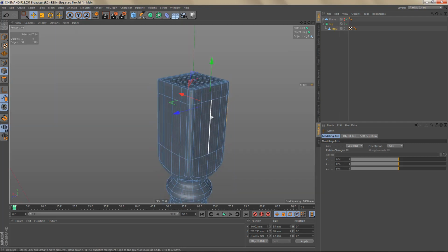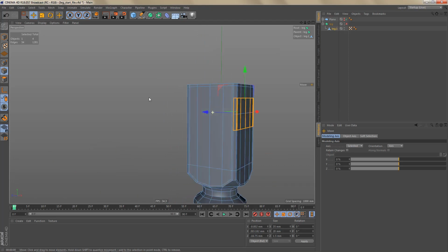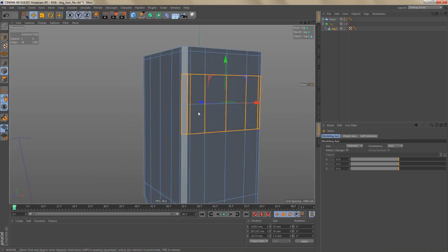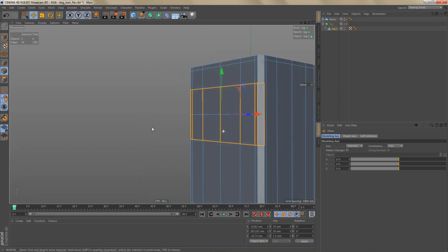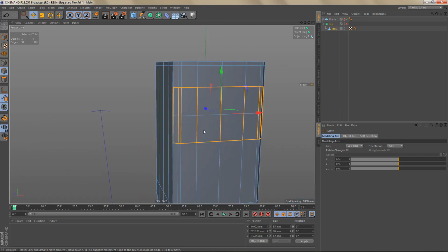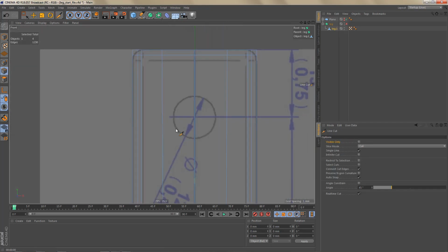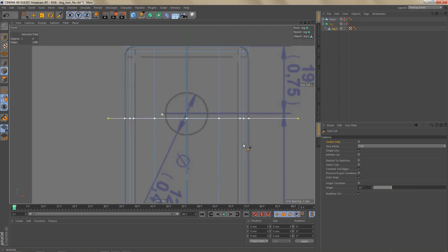Okay, and that is looking a little bit better. And something went wrong when I beveled the edges as well. Let's go ahead and just dissolve all of these again. Let's make another cut. I think it was because I had switched visible only on.